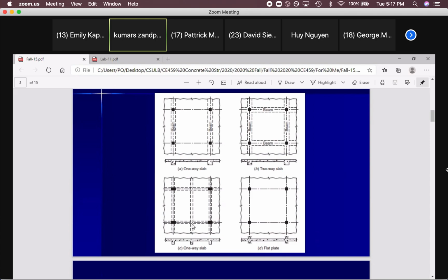If you add a beam here, just remember, if you add another beam on the other side, you will get two-way slabs, 4 two-way slabs. If you have a structure and the architect asks you, I want these beams to be exposed, I like to see that from the bottom, and I want it from both sides, in this case, you have to check for two-way slabs, because you have supports, 1, 2, 3, 4, and the ratio of the long span to the small span is less than 2, so you have 4 two-way slabs. Just remember, you can check what kind of slab you have, and then today we will learn how to design one-way or two-way slabs.